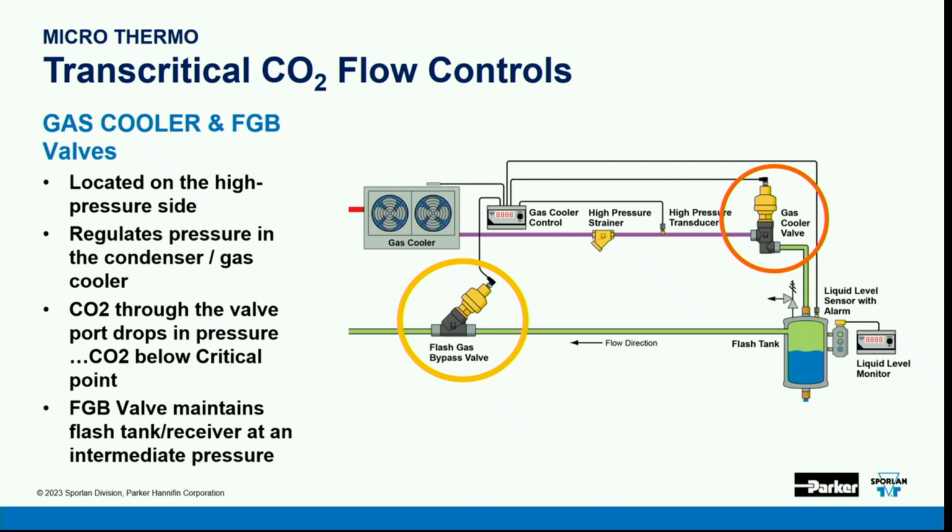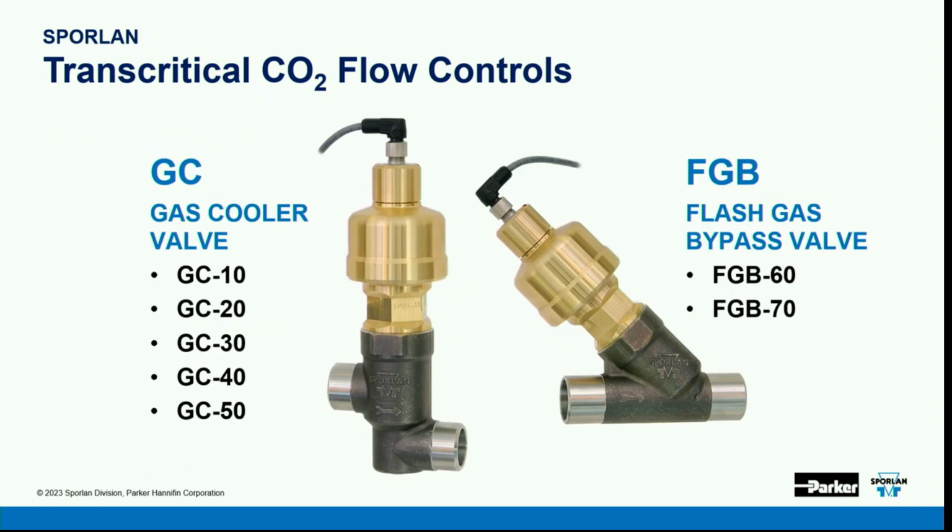So pressure drop across the high pressure valve, and then we're constantly keeping the flash tank around 450 to 500 pounds. What's the pressure coming down to the drop? 800 pounds, 900 pounds. By the time we get through the gas cooler valve, it's now down to 450, 475, 485. And I have subcooled liquid CO2 that I can feed to the cases in the store and do my refrigeration. Any vapor that I didn't get to change phase is just vacuumed out to the medium temp rack and reprocessed, okay? As simple as that.